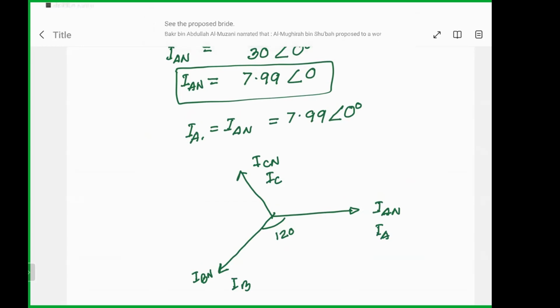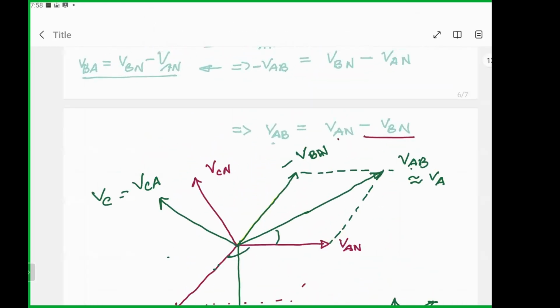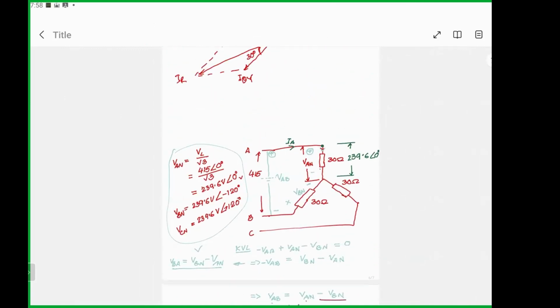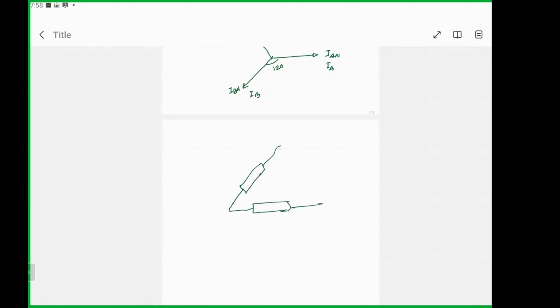Now you can do the same thing, try to get the idea of the same for the delta connection, make this load connected in delta. So if you connect in delta, I can just draw this one. Then try at your home, in your free time, try to find out the phase voltage, line voltage, phase current, and the line current. Try to draw the phasor diagram also.